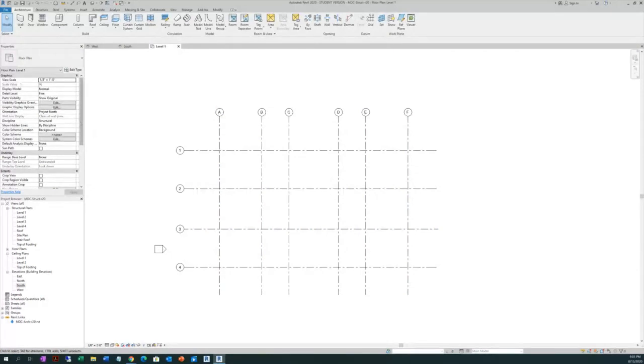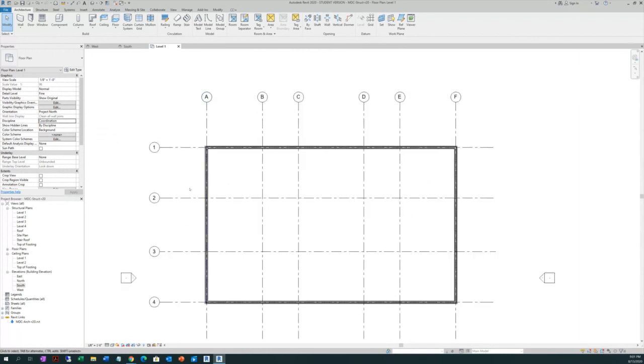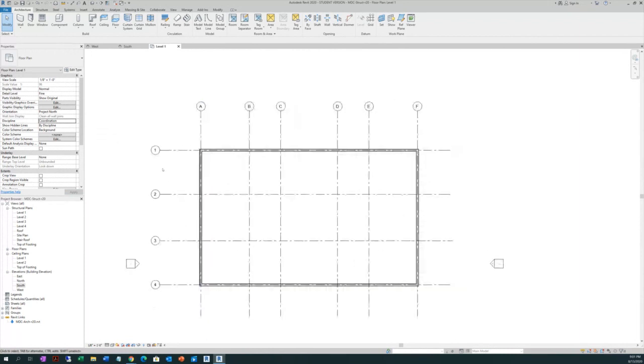If you have the discipline structural, then we are going to do some coordination. If I want to see the architectural on this project, what I need to do is coordination. So in discipline, you click over here and look for coordination, correct? So that is coordination there.